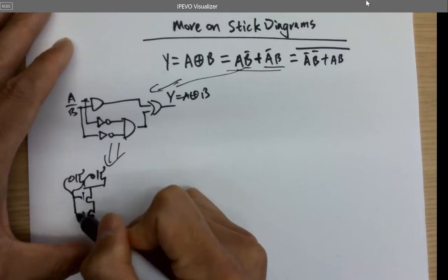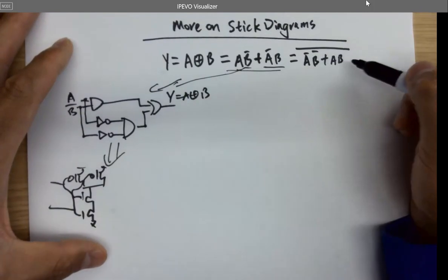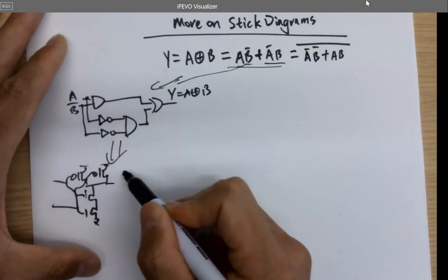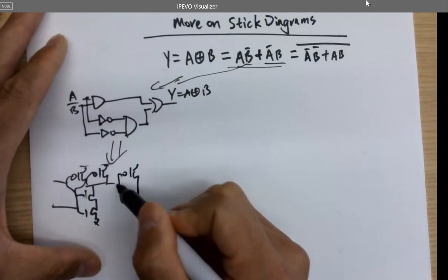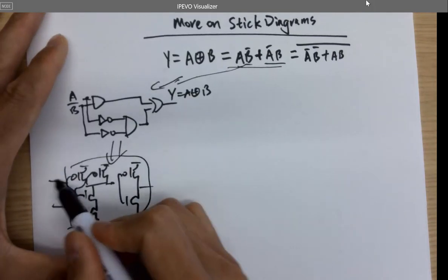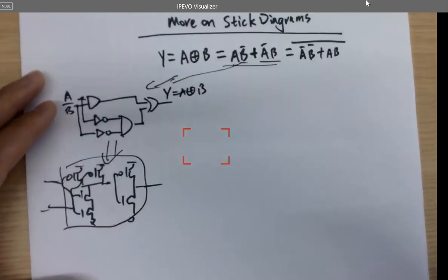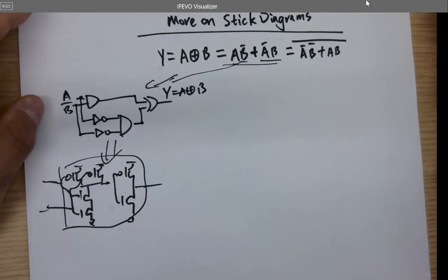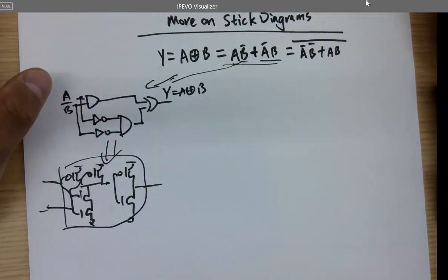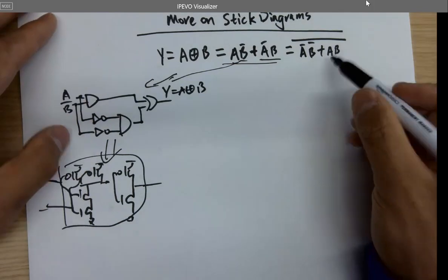So you're saying why you draw this schematic? Yeah, why do we do that? No, why we are taking the effort to draw the transistor level circuit instead of using the gates. Because we know the AND gate, this is NAND gate. So AND gate is basically just the inverting result, right? That's the AND gate, input, output, okay? Yeah, that's right. So you can reduce the number of transistors being used and reduce the footprint of the circuit on the chip, okay? Which reduces the footprint, but also the power, okay? That's why we are taking the efforts to do this.